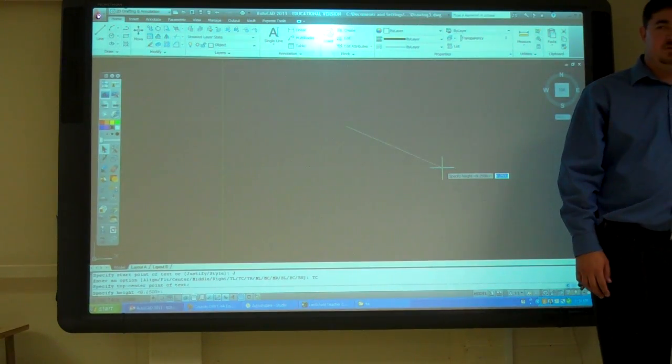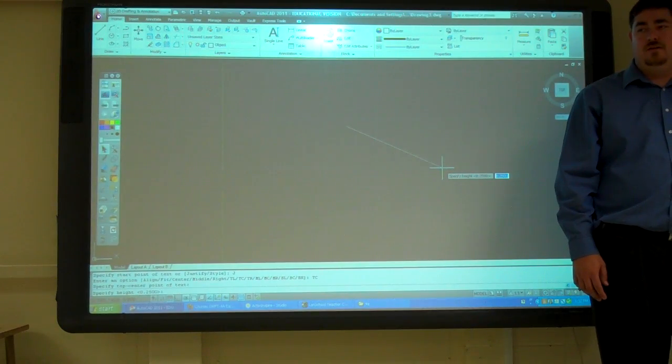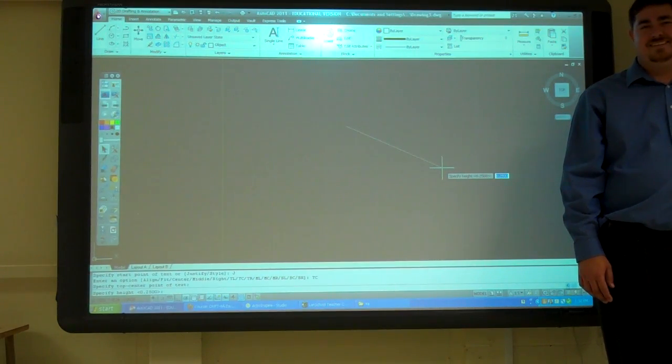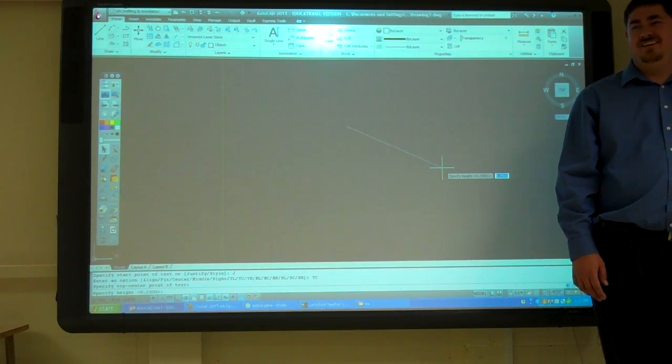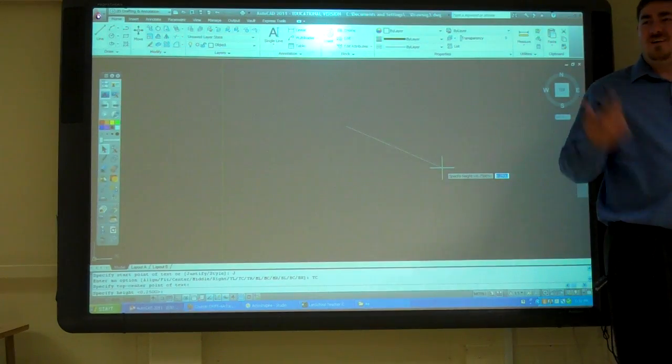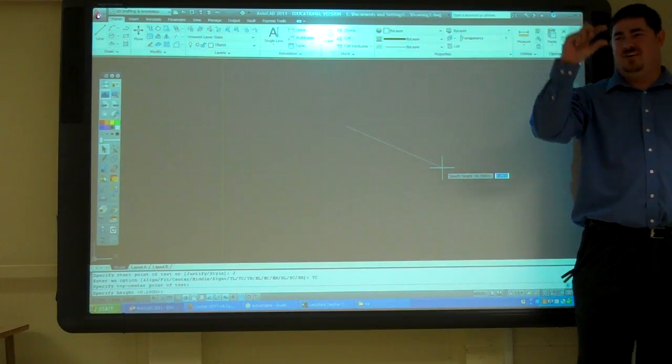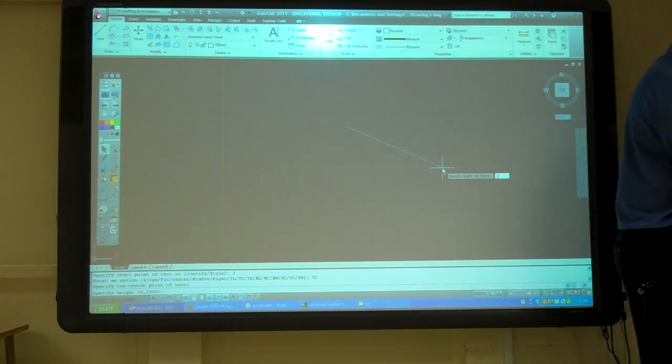Anyone know what height text we usually use? Does anyone know? 1/8 inch? Tricked you, huh? Yeah, 1/8 inch. The quarters, because that last text I had typed on this drawing was the title, and that's taller text. So it's 1/8 inch, 0.12.